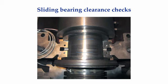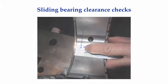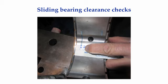For radial bearings, the upper bearing half is removed, a piece of Plastigauge is placed on top of the shaft, the upper half of the bearing put into position and bolted tightly, then the bolts are loosened and removed, and the upper half removed again to observe how much the Plastigauge got crushed. The smaller the clearance, the wider the Plastigauge was flattened. You then use a gauge supplied with the Plastigauge to determine what the clearance was.